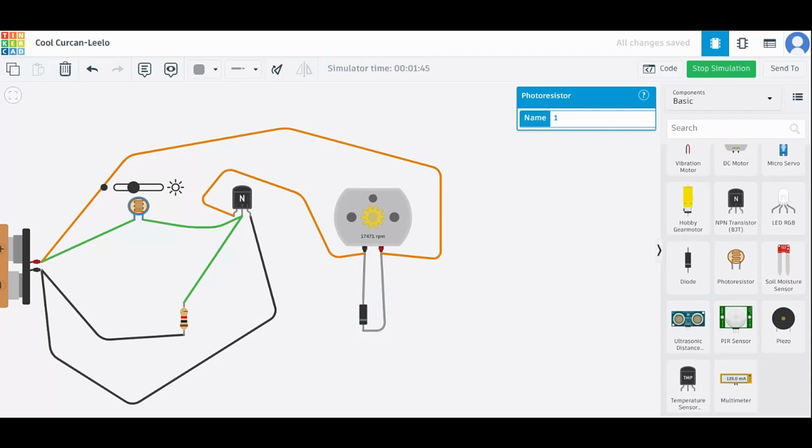So I just did what is called pulse width modulation. On, off, on, off. So now the question is, what percentage is it off? This goes by the name duty cycle. Of course, notice already my forearm is slightly paining. I cannot do this at appropriate time scales. So instead you try to control the base of the circuit using an Arduino, where you can easily specify the duty cycle.